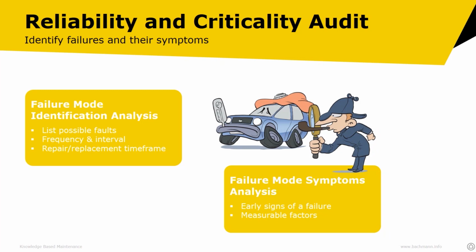Whereas something like a temperature which goes up over the last 3 days before a failure occurs will give you enough time to react. And in the vibration analysis side of things, quite often you may get 3 months before any failure, you'll get a small fault indication that shows you something's starting to happen. And those are the things that are perfect for applying condition monitoring to.